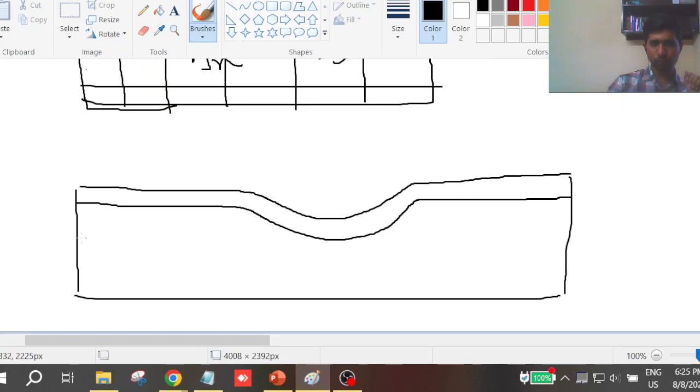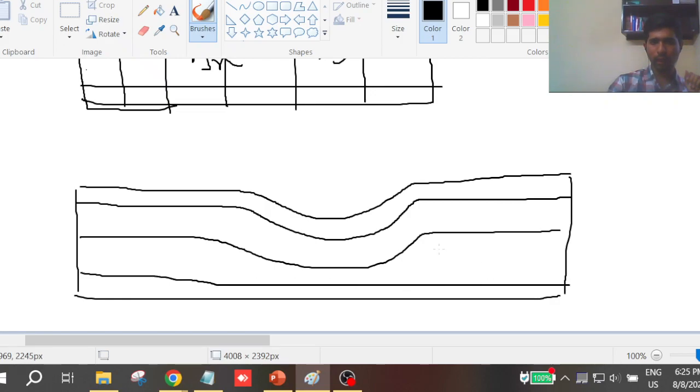This is one type of method wherein you can generate it. Again, this is a structured mesh only, not an unstructured mesh. You have to be very clear about what is structured and what is unstructured mesh. This might look like unstructured, but it is a structured mesh only.